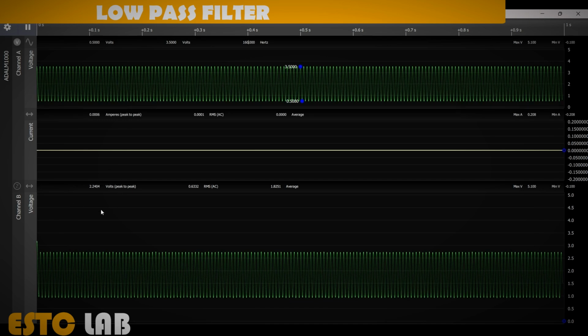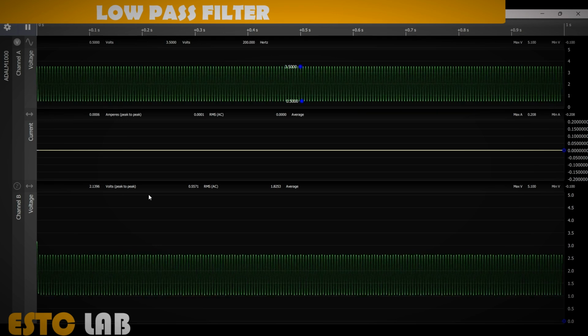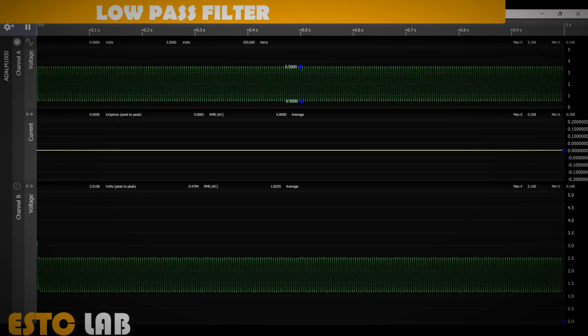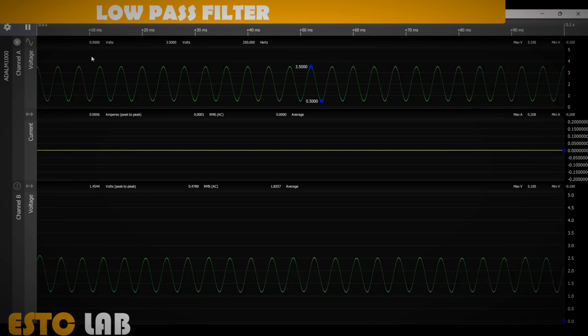this comes to 2.18. So now we have touched the cutoff frequency, and after that this voltage, which is peak to peak, will start decreasing. So at 200, it is 2.13. At 250, 2.14. So we go and change the sample time to something like 100 milliseconds.